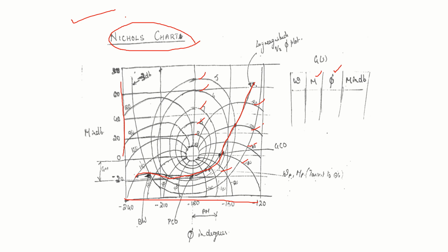After that, from the frequency response graph, how to relate it with the time response specifications. These things we discussed. How to find the steady state error constants Kp, Kv, Ka and all that. How to identify the type number, and once the Bode plot is given, how to find the transfer function. Also I told you. In addition, we discussed M circles, N circles, Nichols chart. So now you can think of using the Bode plot while designing control systems for frequency response. Thank you.